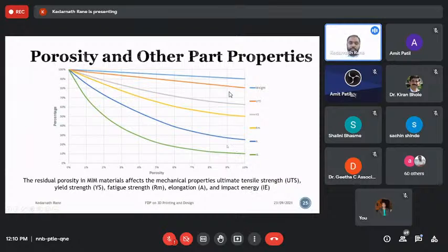The impact strength is a very important characteristic, typically for some defense applications, where there is blast loading. So it is very important to consider the porosity level. That's why I said typically 98-99% density is favorable. 98 to 99% density is important for many applications.